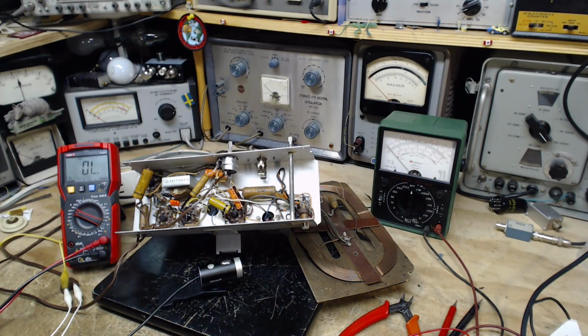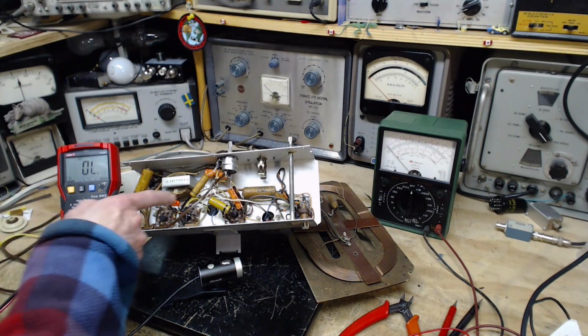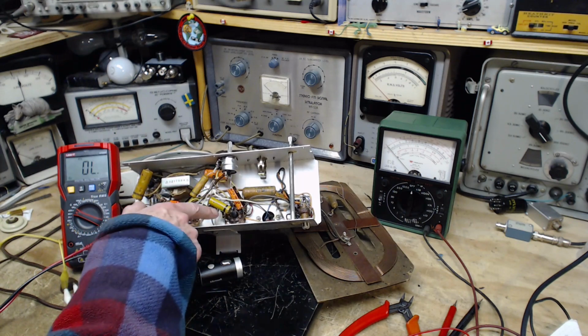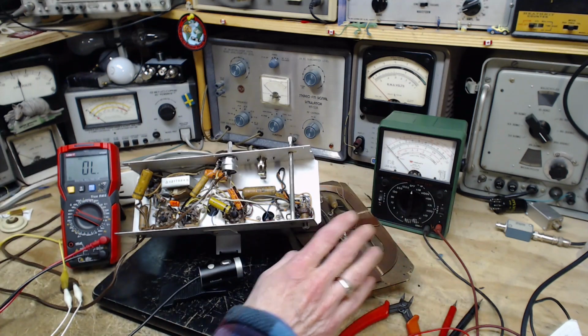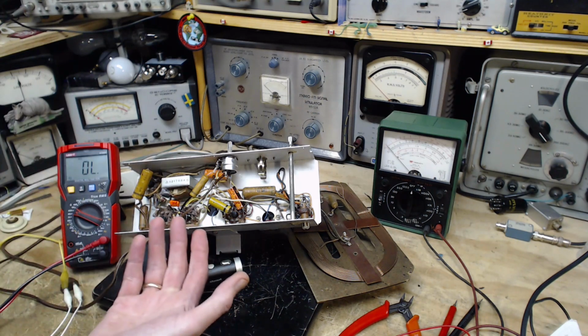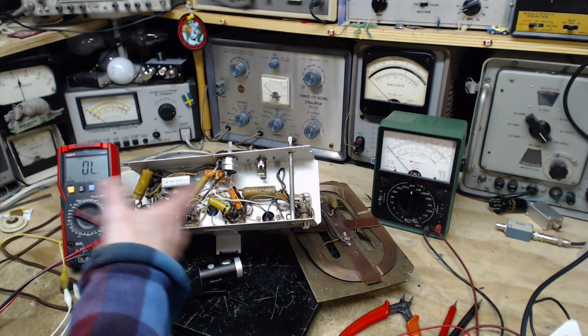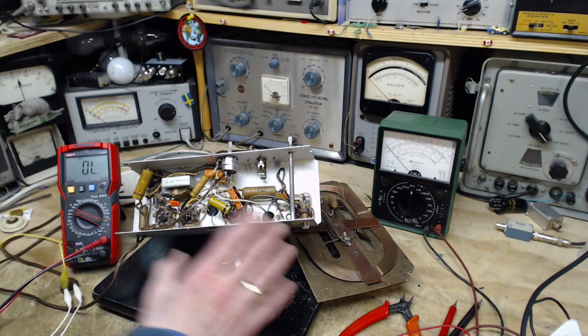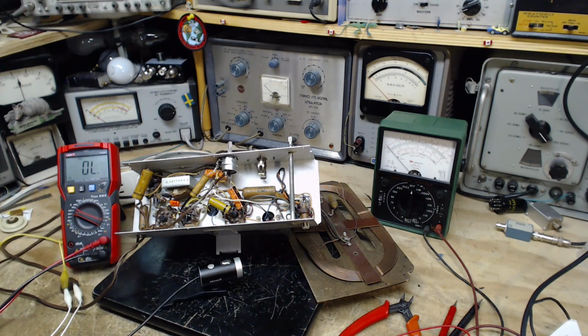Okay, I have the radio back in its original state again. I've soldered this back, resistor's still in, so everything is just the way it was. And we're going to look, and that's why I've performed this resistance test. I got a reading of 220. 220 indicates this resistor is there. This resistor's there. That's about all you can get from that test. And does that make the radio safe? Let's look at the instructions for the next part of the test.